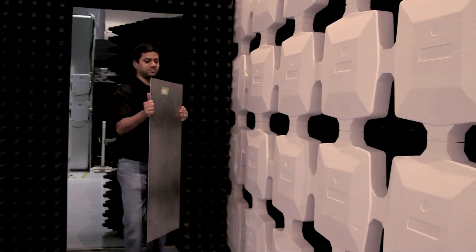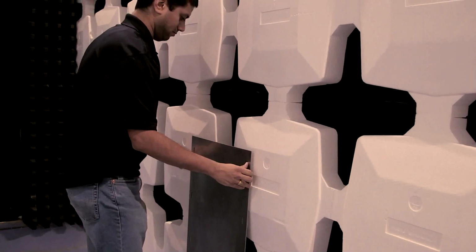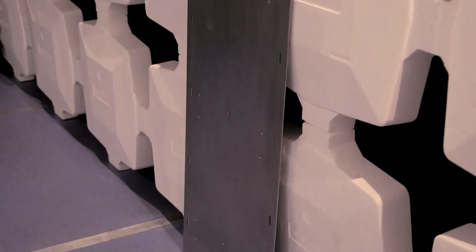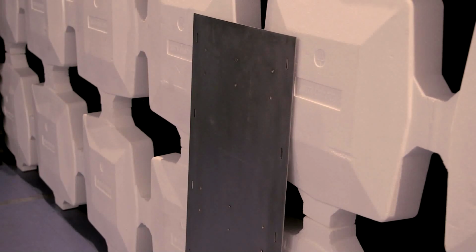Since our goal of this demonstration is to show how to debug a failing chamber, the next step would be for us to get inside the chamber and try to fail the chamber. What we'll do is take a metal plate and try to put it at some specular reflection points on the left wall or right wall or even on the back wall, and we'll see exactly how this metal plate at these specific locations can hurt the chamber performance. Once we do that, we'll repeat the test again, see what kind of result we get, and then we'll go from there.